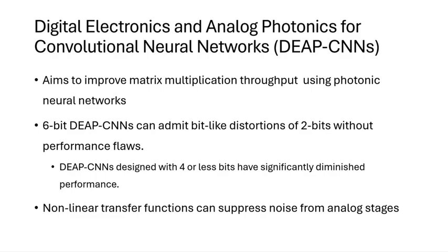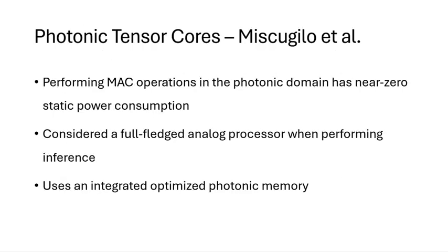However, an unfortunate repercussion of the system is that negative inputs require additional optical or electronic control circuitry. Furthermore, this could result in a loss of precision. The largest bottleneck with the system is the I/O interface through the digital to analog and the analog to digital converters. Next are the photonic tensor cores.